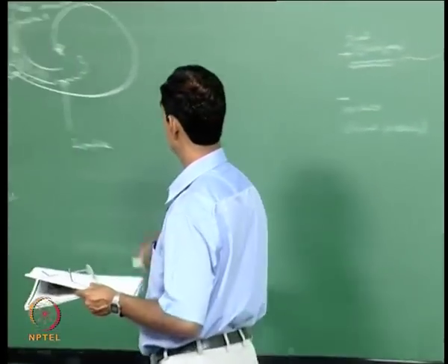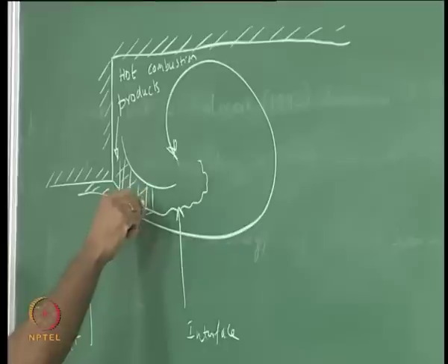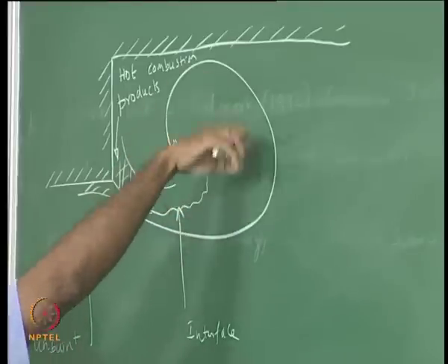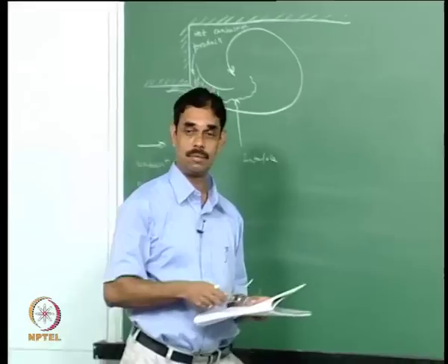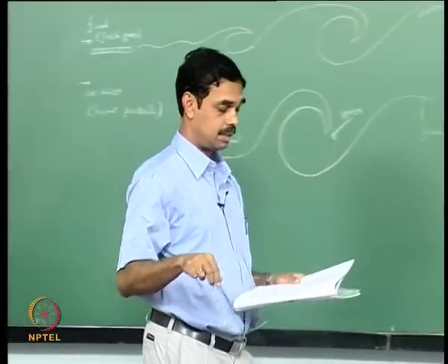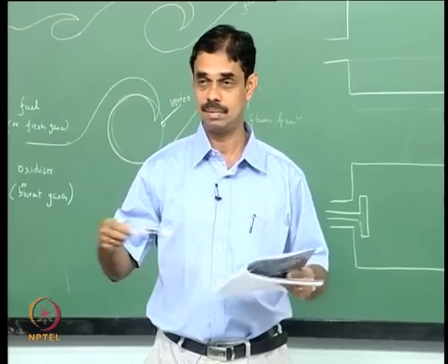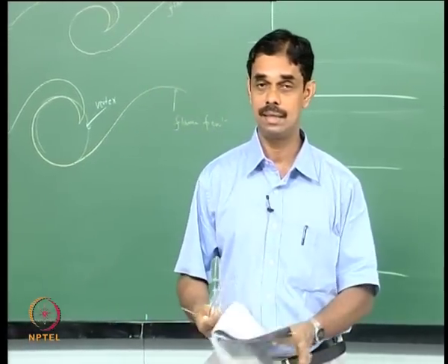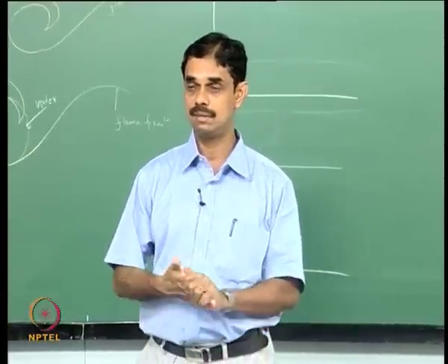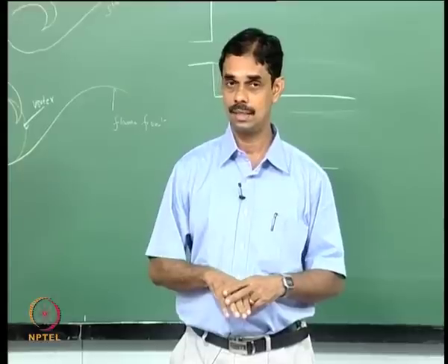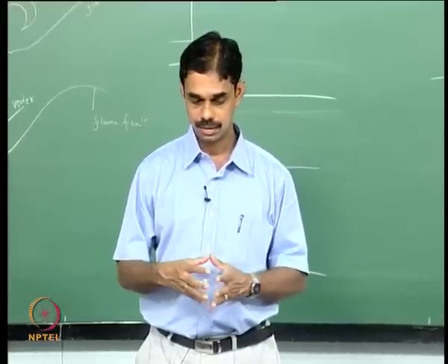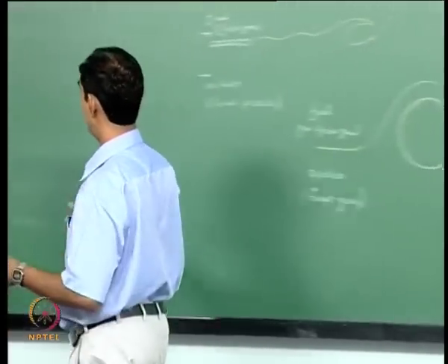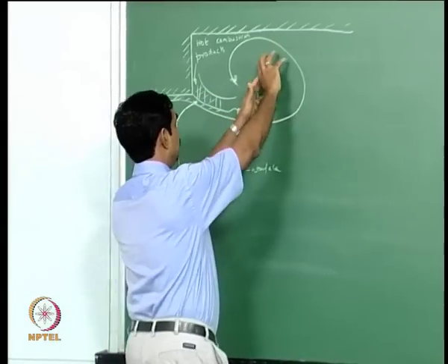and there will be fine scale turbulence which causes entrainment, and so eventually an adequate number of radicals will diffuse or mix into the stream, and there will be a pool which will suddenly burn. So this phenomenon will be quite periodic, and it happens cycle after cycle, and of course if you studied the Rayleigh criterion, it says that if heat release rate is in phase with the acoustic pressure, then you will have acoustic driving. So here there is a delay, so from here you have the mixture coming in here, and at some instant it